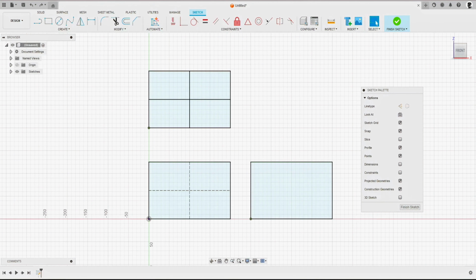So far in this course, we've covered all of the fundamental sketch tools. Now in this lecture, I will highlight some additional sketching techniques to support us in 2D sketching. We will take a look at how to sketch construction lines and how they differ from generic lines. I'll introduce you to the measurement tool, show you how to switch between dimension, diameters, and radii, and we'll also take a look at the sketch palette.